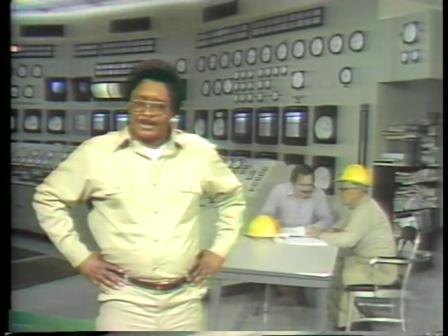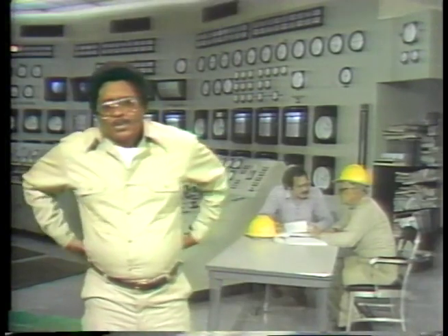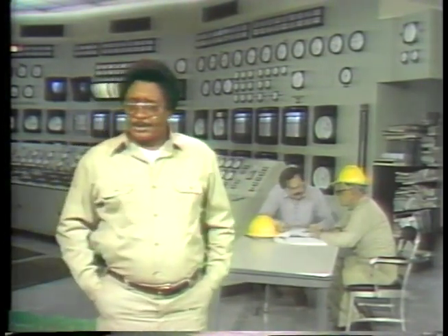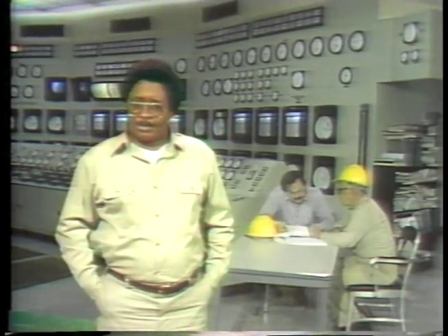In this segment, we've shown you how you can use Tables 1 and 2 of the steam tables to find information about the properties of saturated water and steam. We've also shown you that if you're willing to accept approximate values, you can also find some information about subcooled water in the tables. The steam tables are a valuable tool for finding the properties of water and steam and the state of water in your plant.